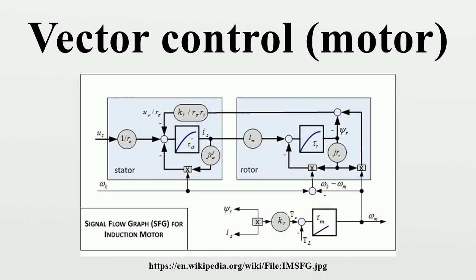Such complex stator current space vector can be defined in a coordinate system with orthogonal components along D and Q axes such that field flux linkage component of current is aligned along the d-axis and torque component of current is aligned along the q-axis. The induction motor's coordinate system can be superimposed to the motor's instantaneous three-phase sinusoidal system as shown in accompanying image. Components of the system current vector allow conventional control such as proportional and integral, or PI, control, as with a